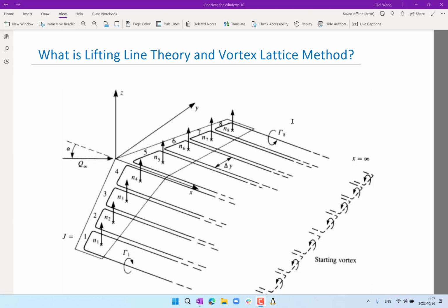I would say the analytical methods nowadays are less and less relevant, because today, if you want to compute the optimal distribution, you can perform a numerical calculation by discretizing the wing into many, many small segments, right? And now, if we know the distribution of the lift, then the amount of circulation on each section of the wing is going to be different, right?